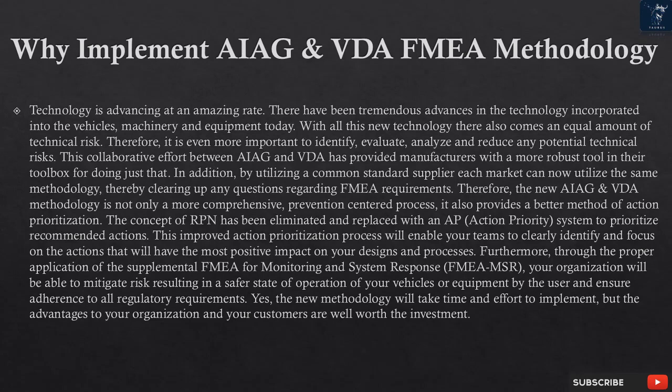Therefore, the new AIAG and VDA methodology is not only a more comprehensive, prevention-centered process, it also provides a better method of action prioritization. The concept of RPN has been eliminated and replaced with an AP, action priority, system to prioritize recommended actions. This improved action prioritization process will enable your teams to clearly identify and focus on the actions that will have the most positive impact on your designs and processes. Furthermore, through the proper application of the supplemental FMEA for monitoring and system response, FMEA MSR, your organization will be able to mitigate risk resulting in a safer state of operation of your vehicles or equipment by the user and ensure adherence to all regulatory requirements. Yes, the new methodology will take time and effort to implement, but the advantages to your organization and your customers are well worth the investment.